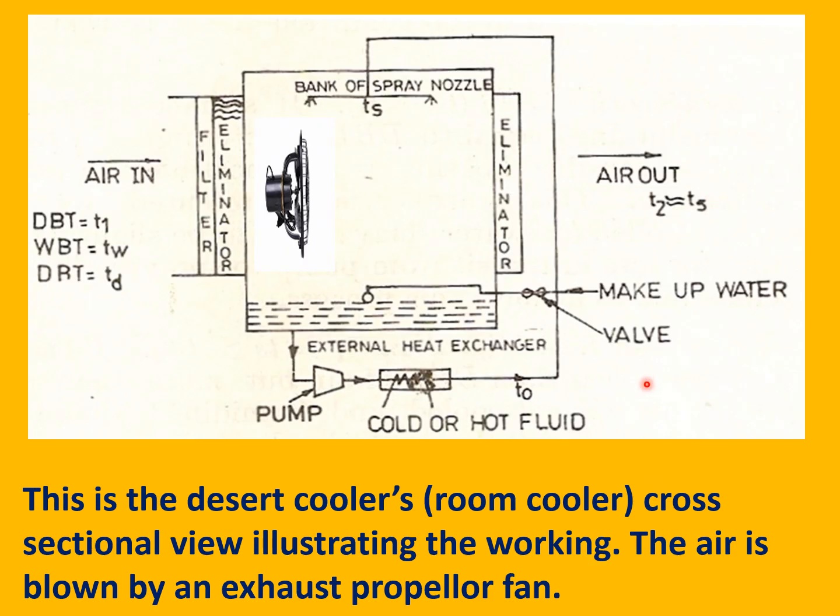We'll try to understand this evaporative process through this sketch, in which there is a water tank below, and we have a bank of spray nozzles provided at the top, and we have a fan, normally exhaust fan, which circulates the air and the water is dripping.